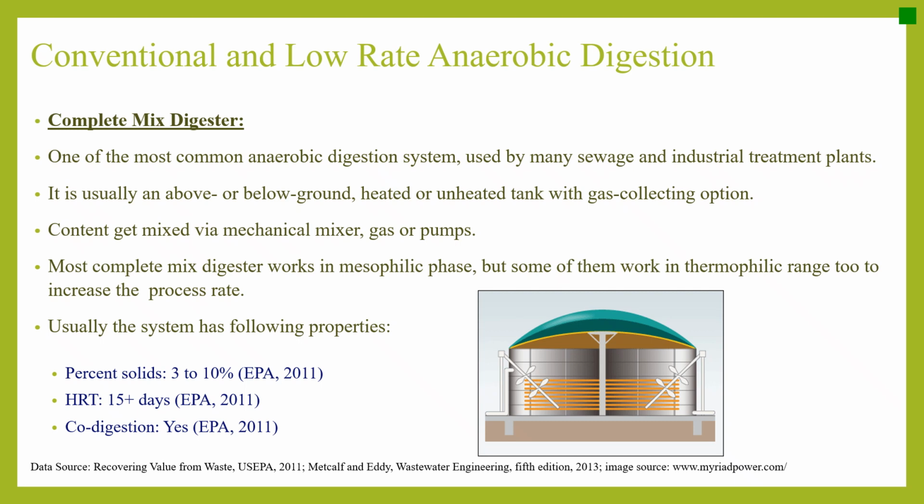Usually the system has the following properties. The percent solids it can handle varies from 3 to 10%. HRT is greater than 15 days, and the system can be used for co-digestion.